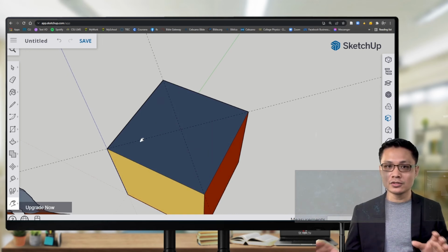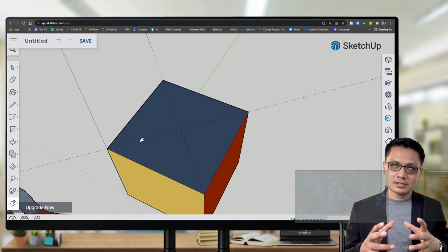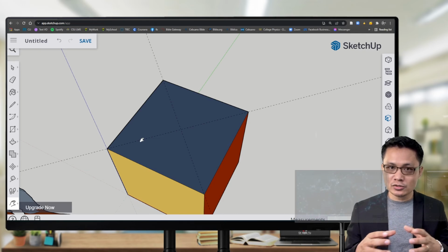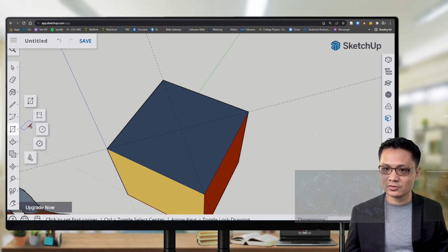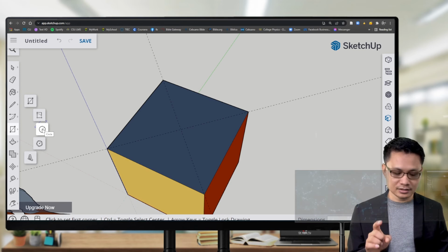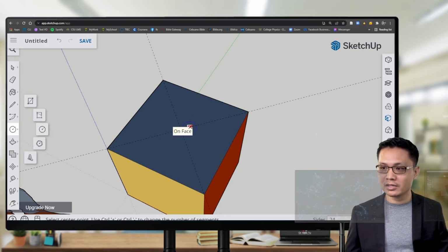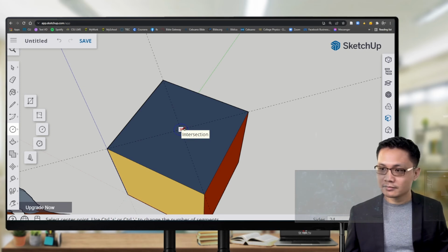So you want to draw a cylinder pole. Say, for example, you have a radius of 2, then you hit C, or you can have this one circle, or just hit C on your keyboard, then move over your mouse towards the center where the X figure will appear.